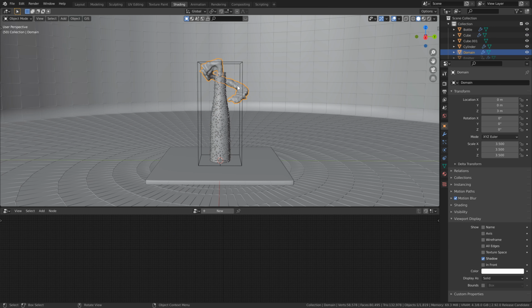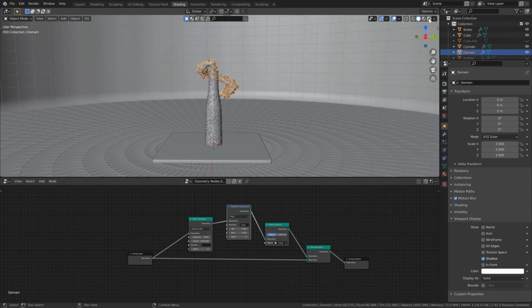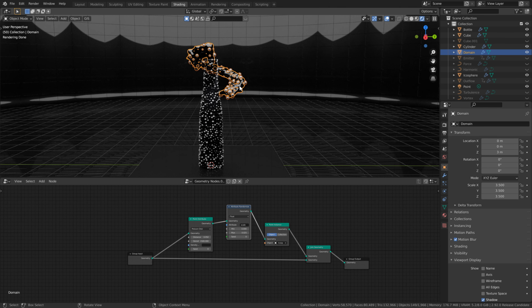Then if you want, you can also add it to the liquid. The best way I found to do this is to simply replicate it this way. If I quickly turn on the shading, you can see that the last thing we need to do is add a material to our particle. So let's head back to the Layer tab. We can select our particle, which is our icosphere. Head into the materials, click New. Then again, let's bring the value down into a deep gray, roughness all the way down, and let's bring the transmission all the way up.